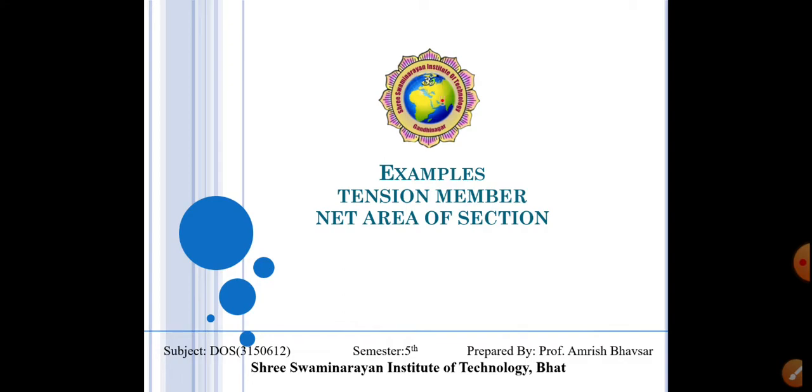Whenever we find the capacity of the member during rupture, whenever we drill the member to make a hole for the bolts, the rupture of that member depends on the net area of the member.